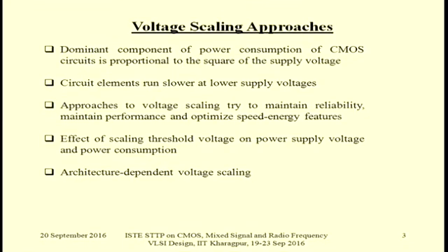And regarding the speed-energy feature, we shall see that the product of energy and delay can be optimized, and thereby we can theoretically obtain an optimum voltage. We can slightly exceed that voltage without causing much harm. Also, there is the effect of scaling the threshold voltage along with the power supply voltage. There is also a trade-off.